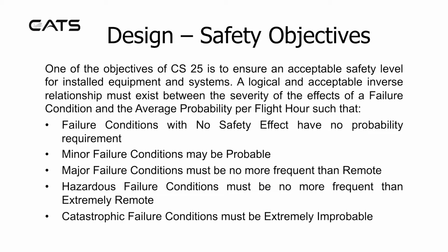Design safety objectives. One of the objectives of Certification Specification 25 is to ensure an acceptable safety level for installed equipment and systems. A logical and acceptable inverse relationship must exist between the severity of the effects of a failure condition and the average probability per flight hour, such that failure conditions with no safety effect have no probability requirement. Minor failure conditions may be probable.